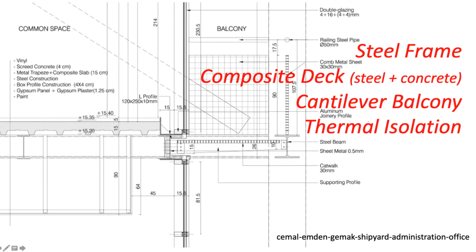We've got insulation protecting that thermal bridging that wants to happen around the steel. But we also have this really great bracket that is holding up a tapered piece of steel that is basically holding this entire deck. So that's one way of doing it, cantilevering a piece of steel off of the frame devices themselves.